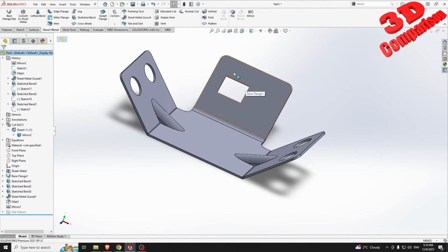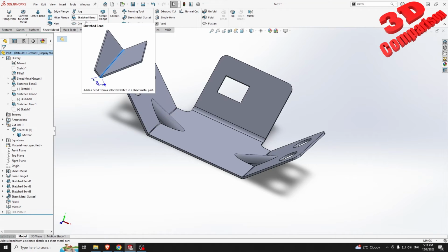But for other elements, like we saw previously over here with that sketch bend, there are some problems over there, since the part has a fixed part and another part that will be angled according to that. And that's why usually you don't use mirror like that. You can use it underneath sketch, you can use it afterwards for other elements, but directly within various jogs or sketch bends that are added to the part, it's not recommended to use that mirror tool.